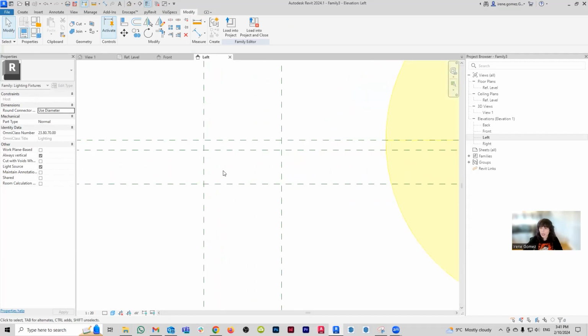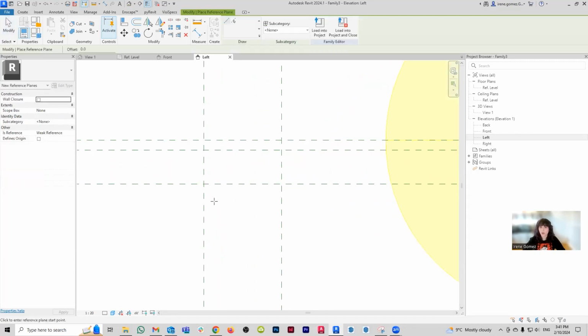So the thing is that you kind of have to be careful, because if I just do a reference plane that mimics what is the inclination that I think that sheet has, which I think is maybe something like 45 degrees, I'm just guessing. The problem is that when you create a reference plane, you have to think about it almost like when you're working with a 3D printer and you have a base and the printing is always on top and perpendicular to that base. So that is how your reference planes work.